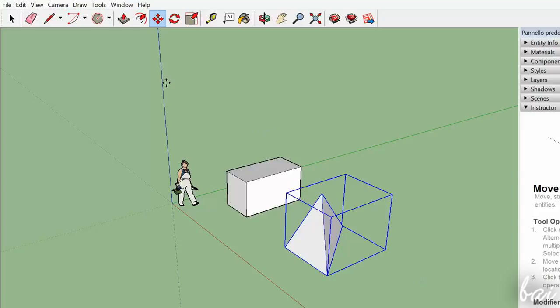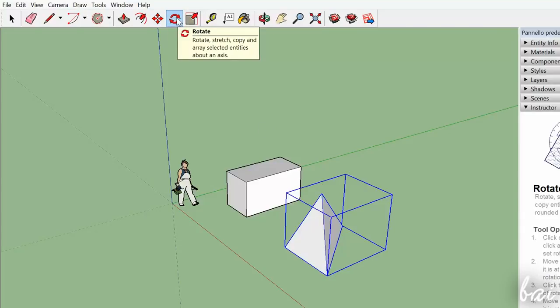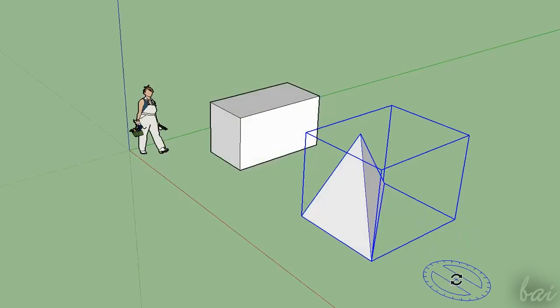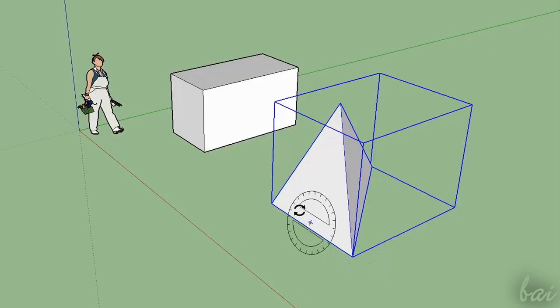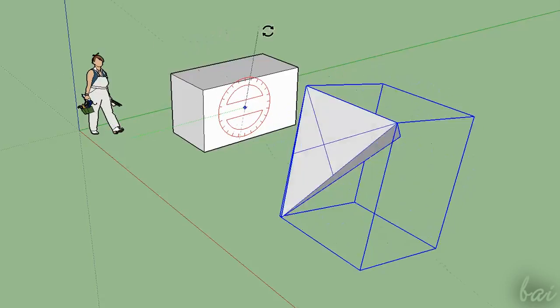The Rotate tool is used to rotate objects. Firstly, you need to fix the rotation point. The goniometer will be fixed and this will be adapted to the plane it finds. Then fix a second point to define an axis and then define the angle of rotation to rotate.